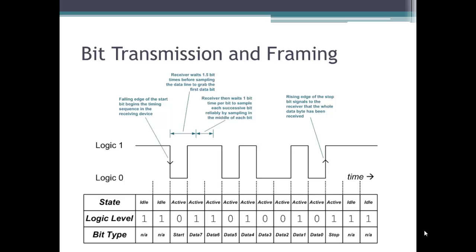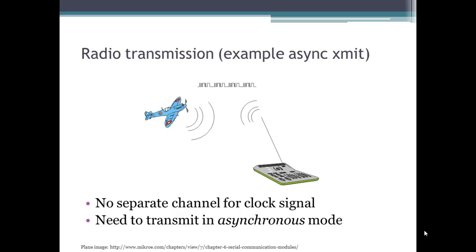And finally, all the way at the right side of the page, the rising edge of the stop bit signals to the receiver that the whole data byte has been received, and the receiver then does whatever it does with that data byte once it's been parsed in.